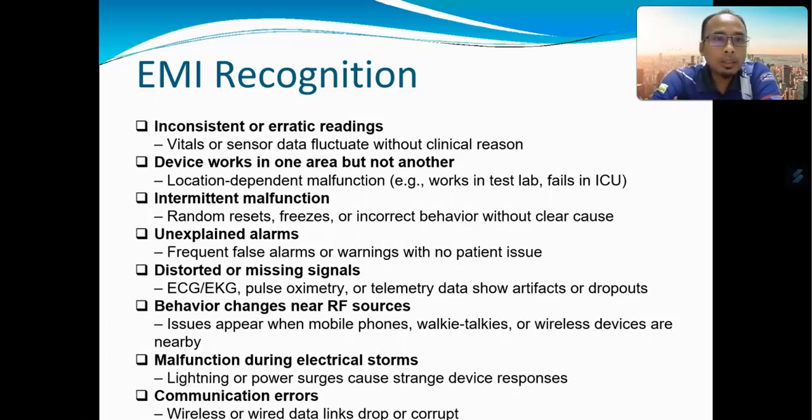Secondly, EMI can be recognized through a device that works in one area but not in another area, which means that the device is location dependent.